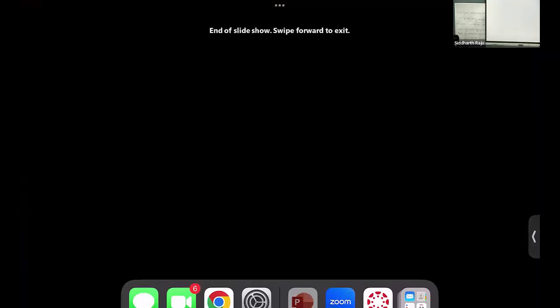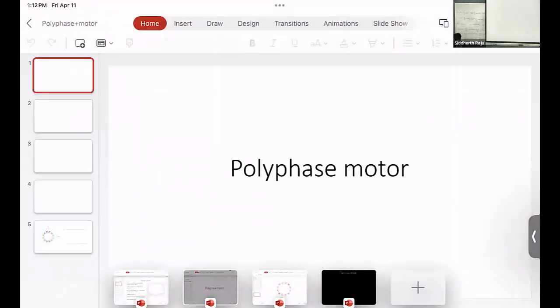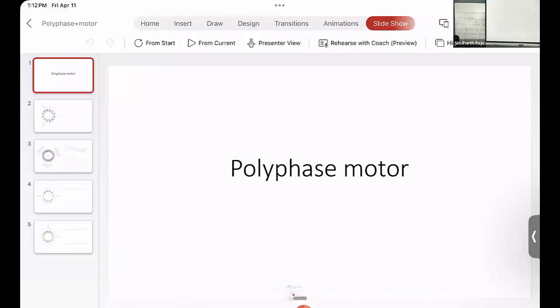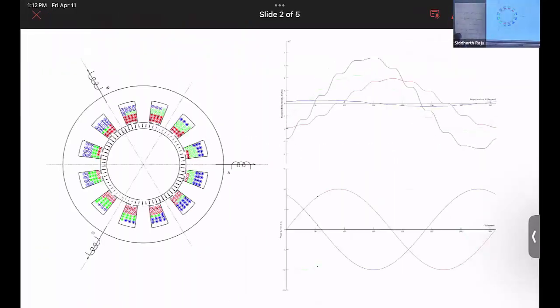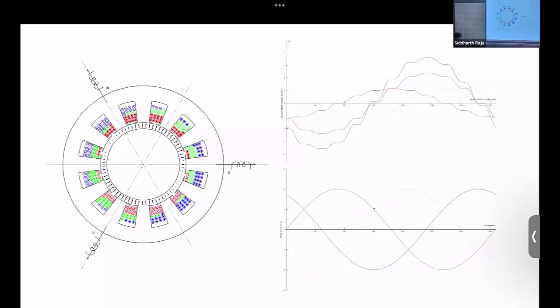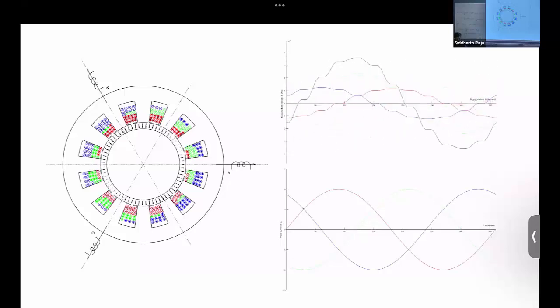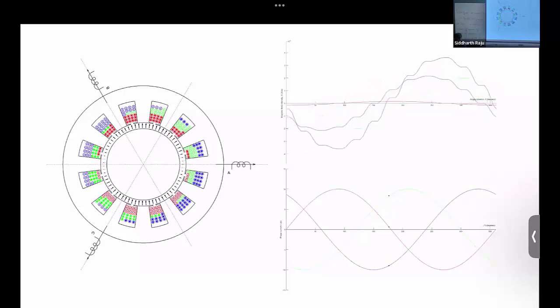Okay, so next what we're going to be looking at is let's do the polyphase thing. So far we have looked at the three-phase case. I said that even in a two-phase motor, you do get rotating fields and the motor will rotate. In a one-phase case, clearly it won't rotate because we already saw the one-phase case. When we just looked at one winding, A-phase winding alone, we got the standing wave and that's not going to rotate a magnet. We've already seen the case.